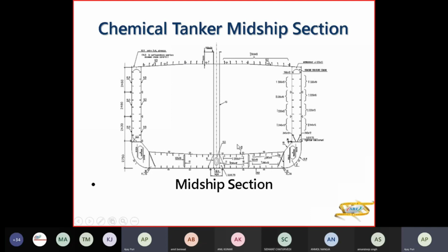The reason being, chemical tankers require extensive cleaning. Maybe you're loading methanol and other cargoes that require absolute precision cleaning. That's why you have a wall wash test in chemical tankers before loading methanol. So even a hair or a small thread can fail the tank. If your longitudinals were inside the tank, the old cargoes would have been sticking there, which you can't clean, and that might contaminate your cargoes.